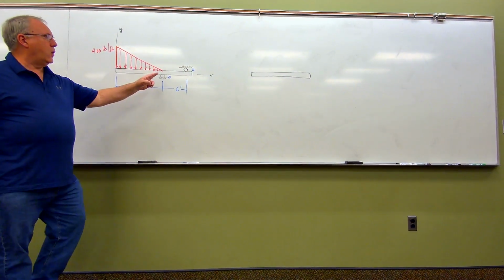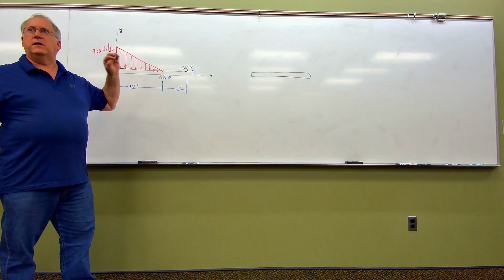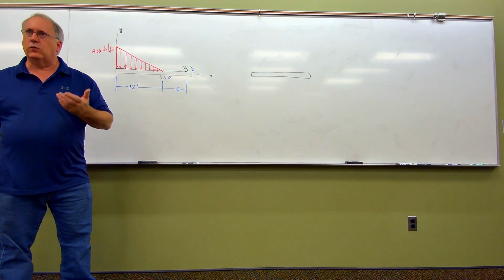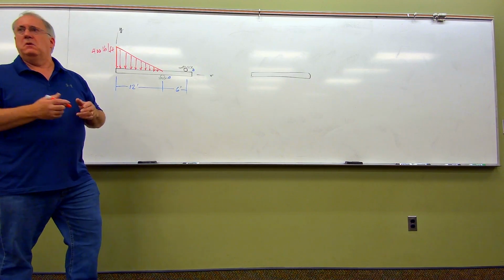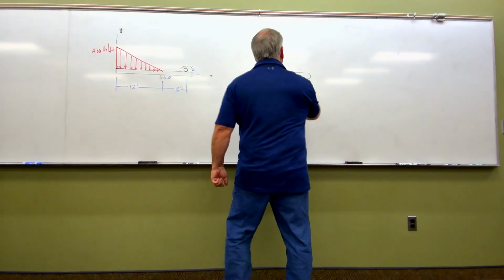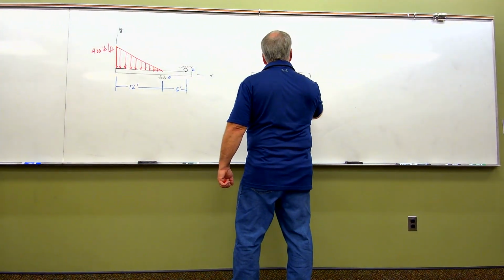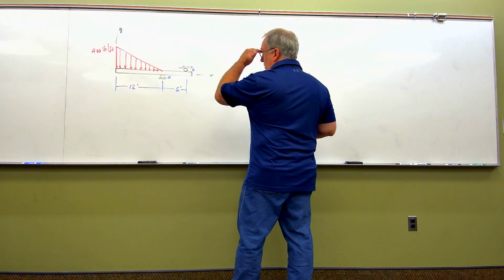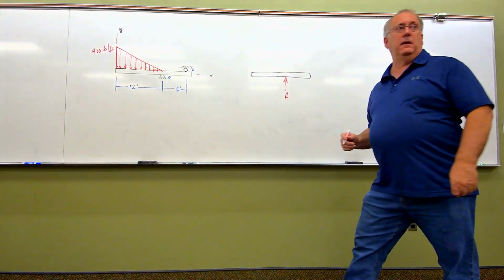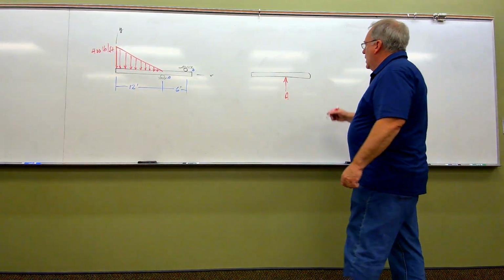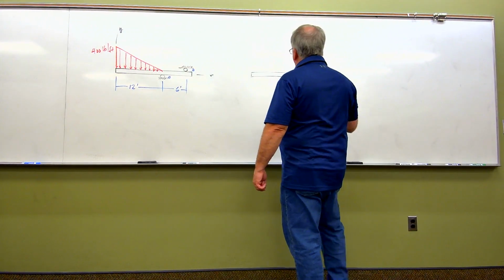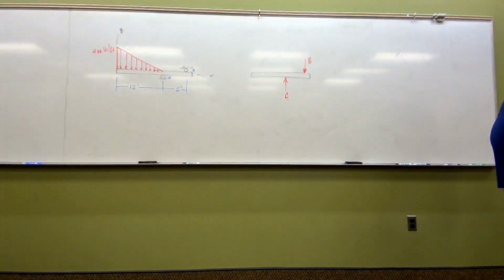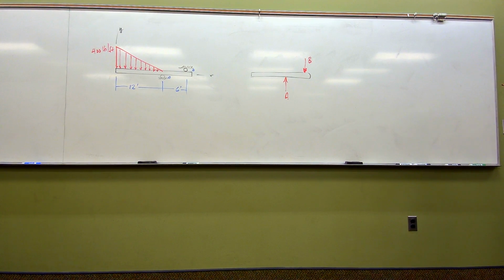Now, we know we got a roller right here, folks. From the earliest part of this course, we've always modeled roller forces as a single force normal to the plane of application. That hasn't changed one bit. So here, I'm going to have some force on this that may look something like this. I'm simply going to call it force A. Over here for roller B, same thing, nothing's new here, it's just a roller. So that means I'm going to have some force over here, let's call it B. Now, as we've said many times over, do we know that that's the right directionality of these forces? No. Do we care? No. We just apply them as they are.